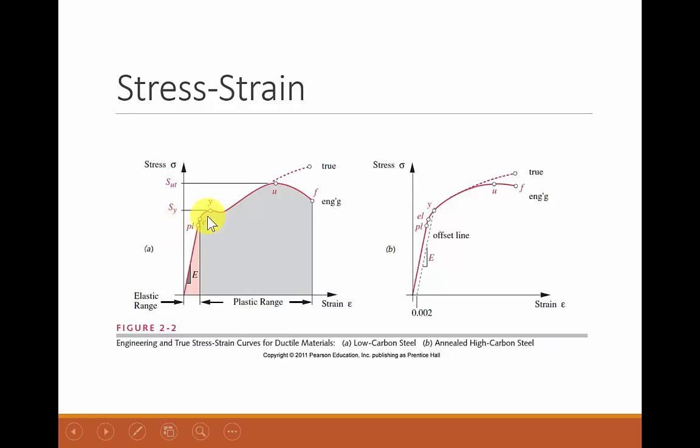So some types of material, you can continue to strain the material all the way until it reaches some sort of ultimate, and then if you notice, for the same amount of stress, you'll now have a decrease in the amount of strain. What this means is that if I put this amount of stress on it, S ultimate, the part's going to fail, and what's going to happen is the diameter is slowly going to get smaller as it begins to stretch, and since the diameter is now smaller, it'll be able to strain even further, and so this is what we would actually exhibit in the lab.